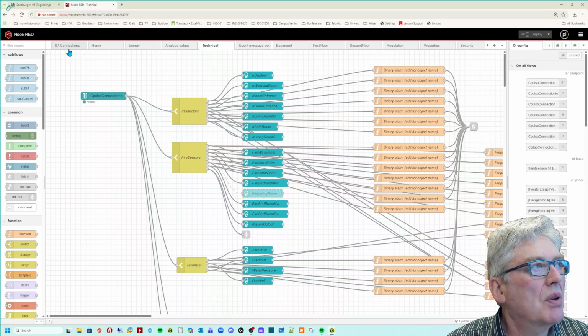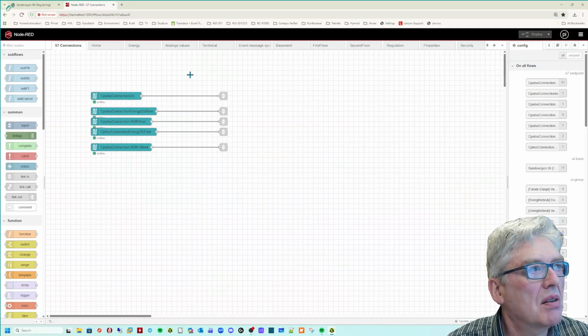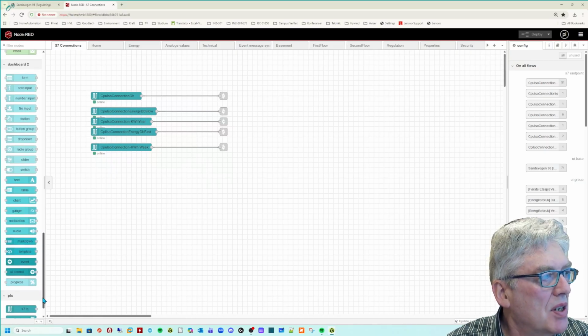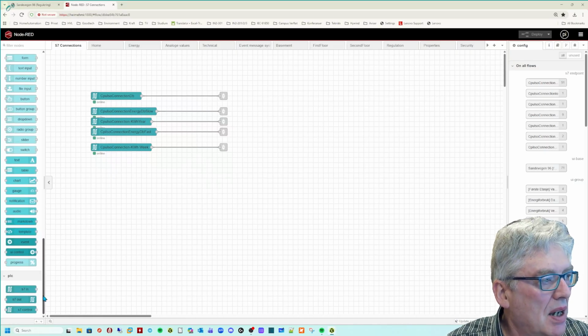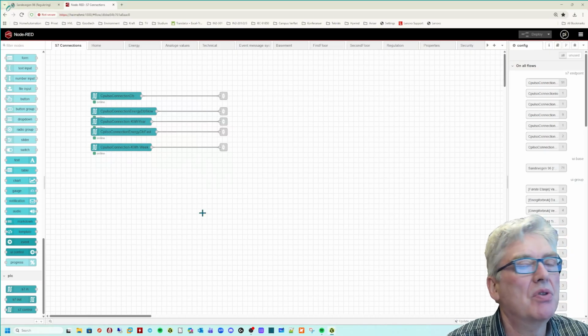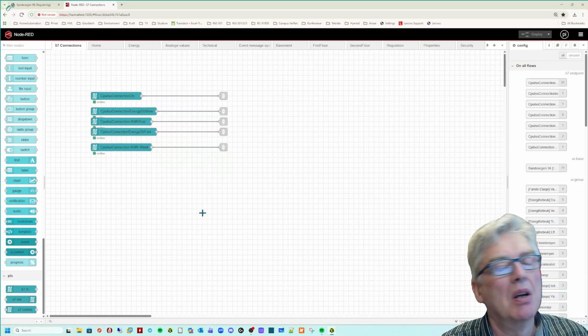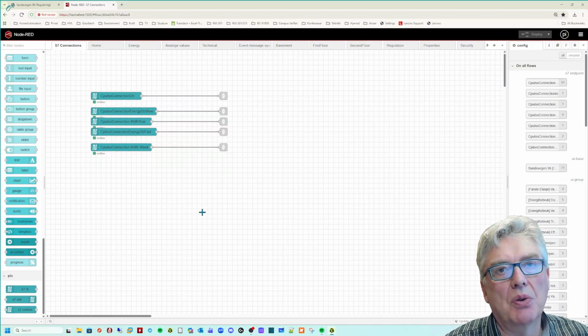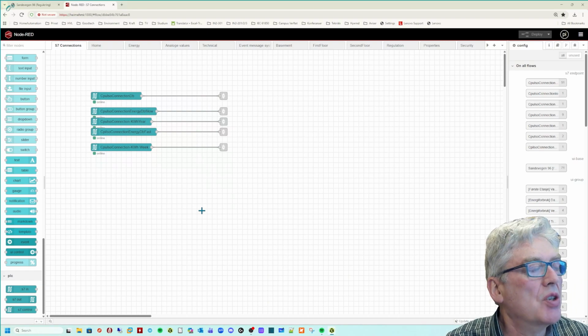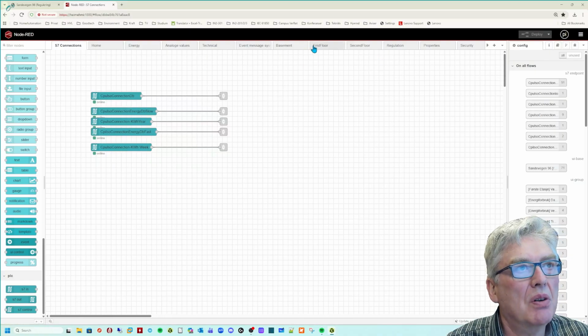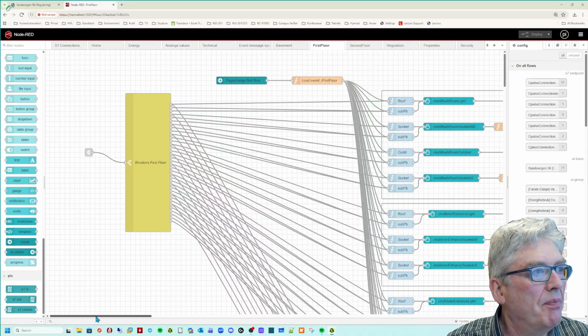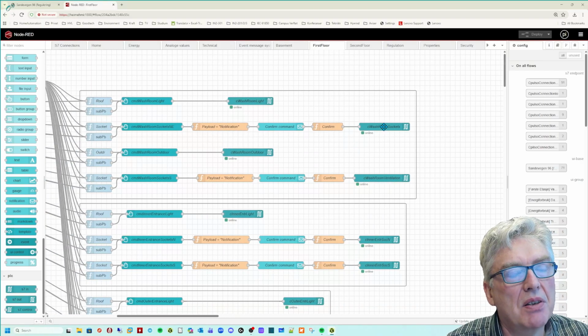So if we go and look at it, here are the Simatic. Of course, you can get some Simatic PLC. Where was it now? Here, you can get a driver for that, a communication driver. It's using an old type protocol, but it works. For more modern CPUs, you would of course use OPC-UA for this kind of communication, and so on. So here the data is just collected and then transmitted to where I use it. So let's say if we were on the first floor, of course here is the writing to the PLC.